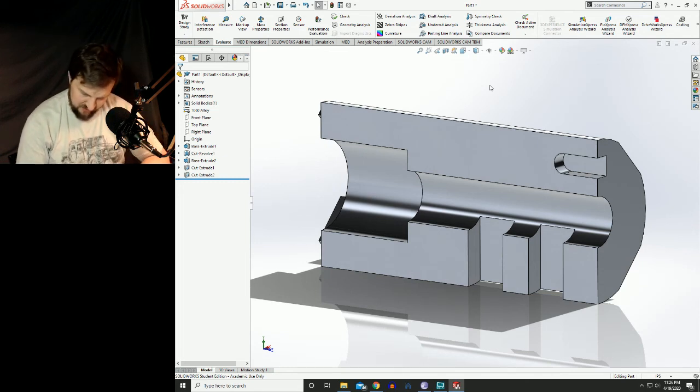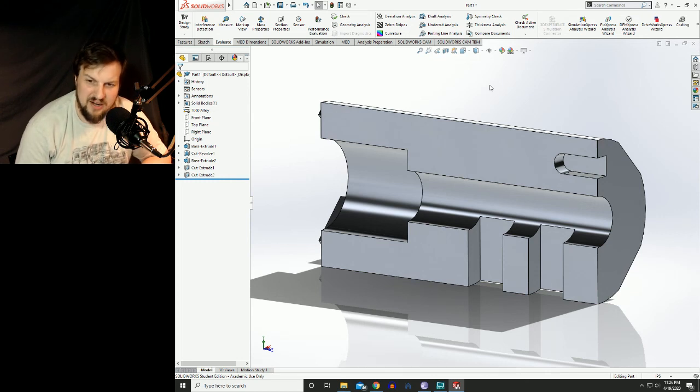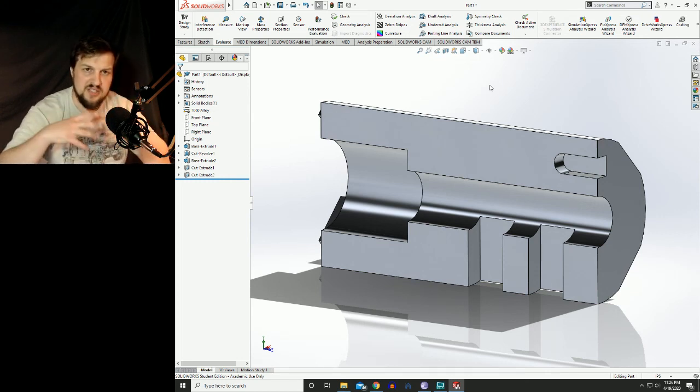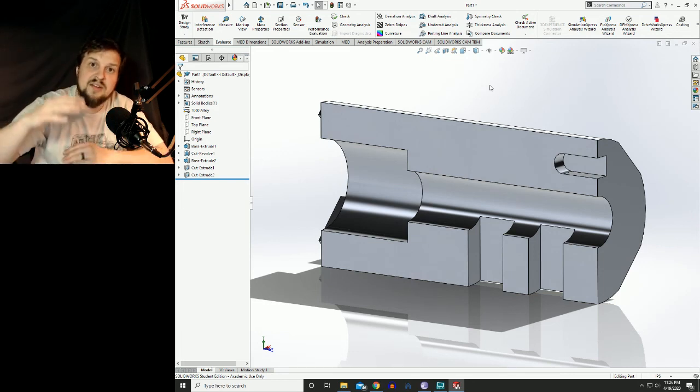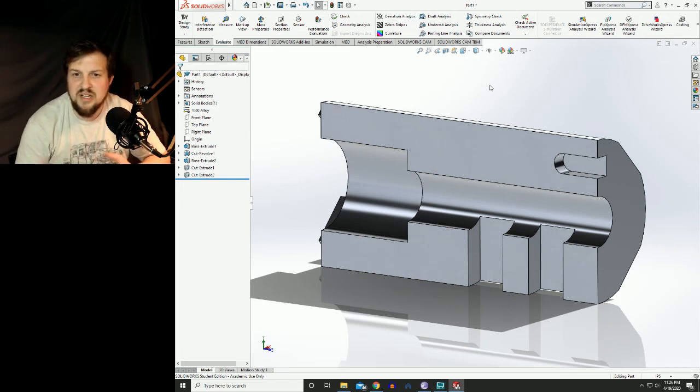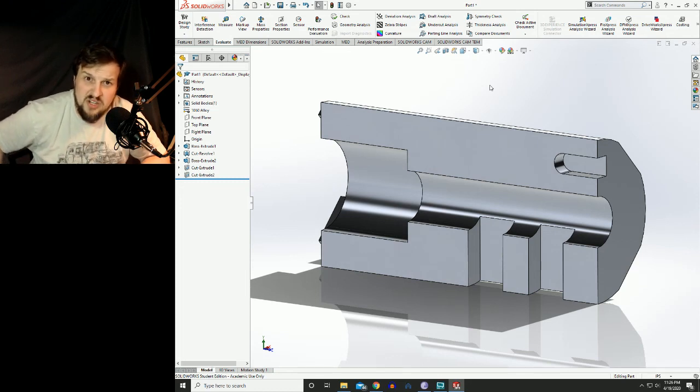How big is this? Big or small, it doesn't really matter. Dimension the one on the outside first. So that first, once you get your entire profile made, and we're talking about this the second assignment. Once you get your profile made, go ahead and dimension it, and remember that first dimension is going to scale. So the first dimension, go ahead and dimension the outside, because that's going to scale everything in or everything out. Don't do the inside one. It's a little easier when you scale the outside one in this particular case.